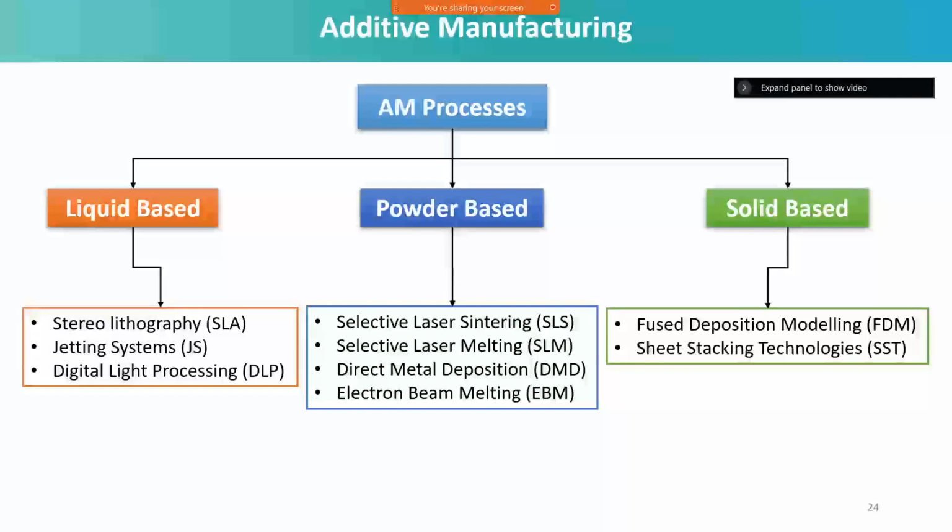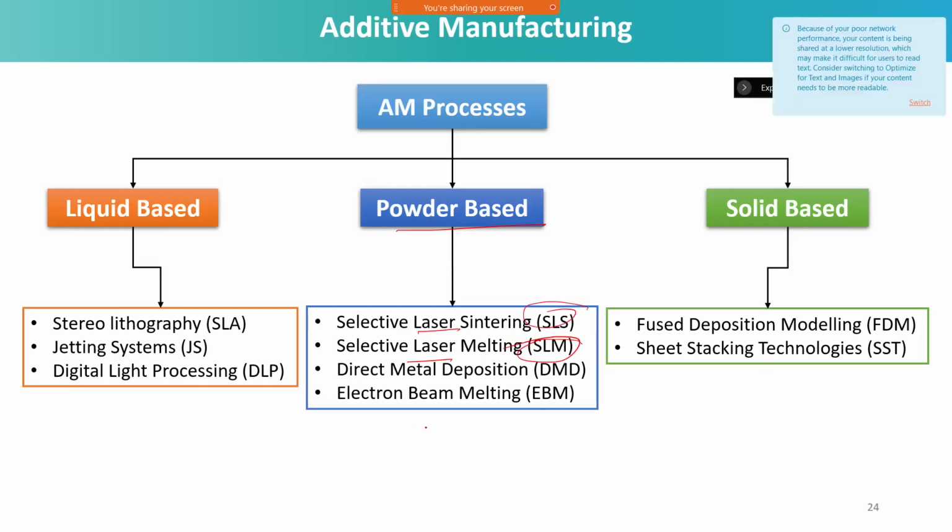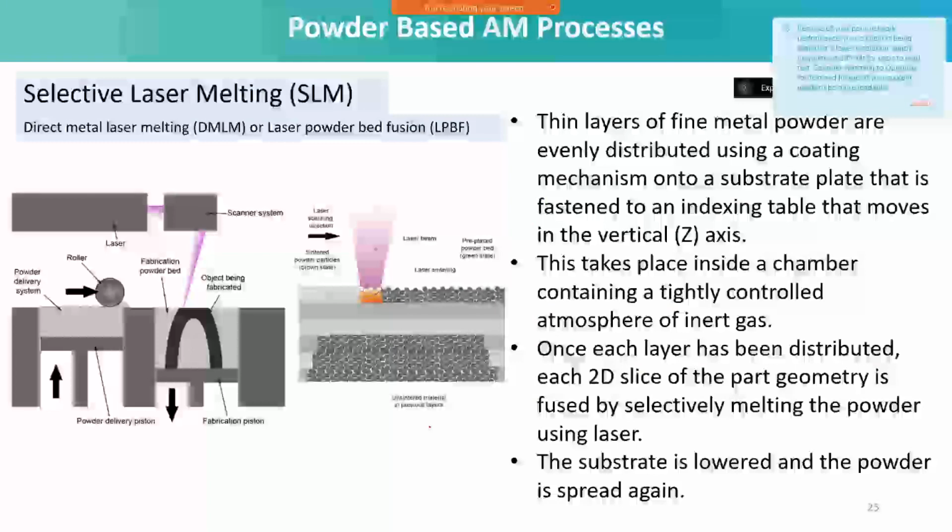So finally, in the additive manufacturing area, we just started working as we got a very good metal AM system. Among the different classifications, laser based additive manufacturing is inevitable, even though electron beam additive manufacturing is coming slowly into the market. If you talk about any powder based system, without laser you cannot realize that kind of buildup of the component. Either it's selective laser sintering or selective laser melting, and you can extensively think about using laser.